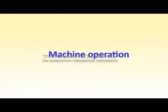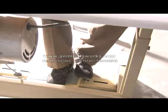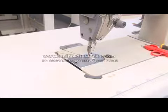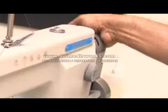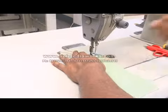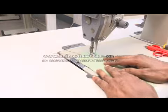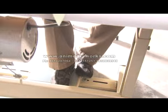Operating the sewing machine. Position yourself in the center of the needle bar. Sit upright and place both feet on the foot pedal. Make sure the adjustments are correct. Place material between the pressure foot and the throat plate. Bring down the needle using the hand wheel. The needle should be placed at the exact point the stitching should start. Gently press the foot pedal to achieve the right speed.